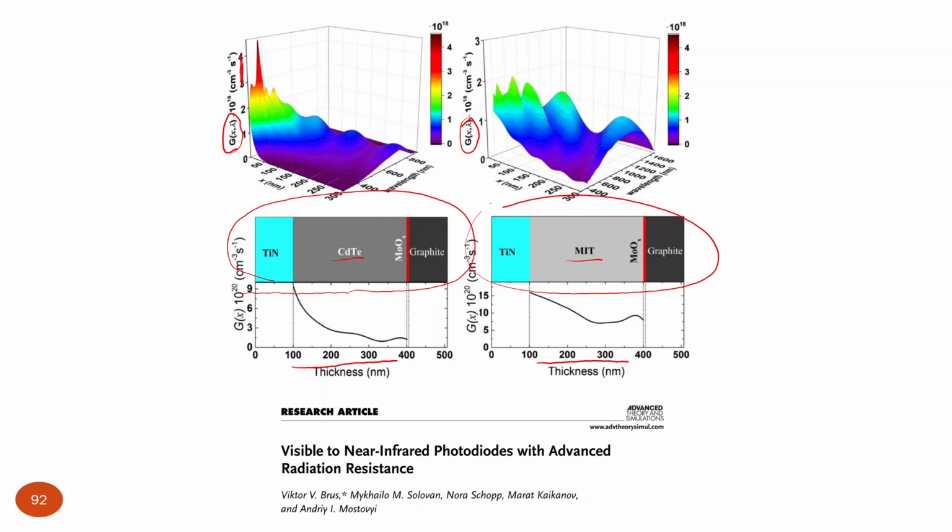And we have it as a function of wavelengths. You see, we go from 400 to 800, and here is why the wavelength range, because it's narrow bandgap material, from like 400 to 1600. And at each wavelength, within this photosensitivity region, we can predict the position distribution of this photo generation rate.